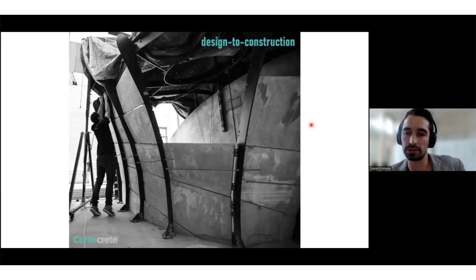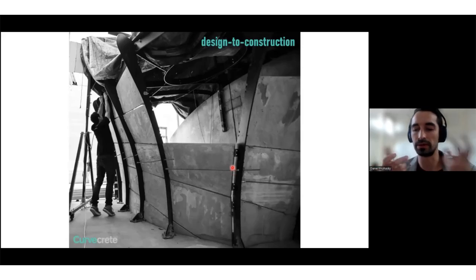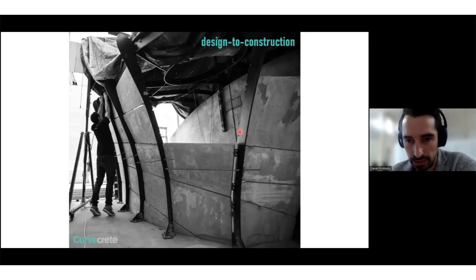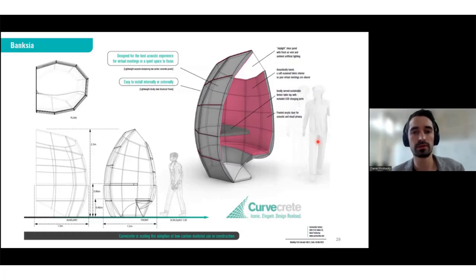Some of the challenges on this project were how we were hooking the panels in. The tolerances were quite critical. How precisely we were casting the panels was still in development because we developed the robotic system at the same time as casting the panels. So we wanted to develop that a bit further. Here you can see, maybe small here, there are some hooks that the panels had pins that then basically hooked onto. We thought that we could maybe integrate that structure a bit further.